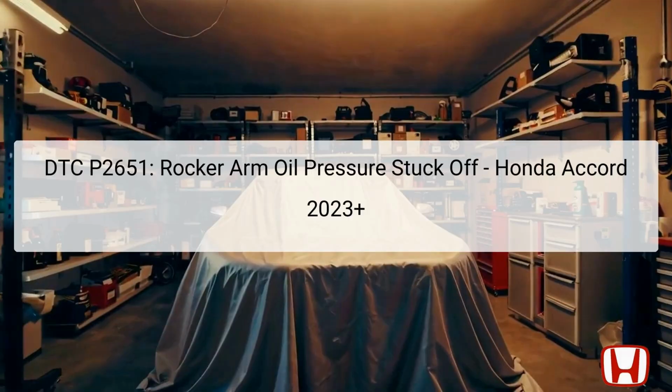Welcome to this troubleshooting guide for DTC P2651, which indicates that there's a problem with the rocker arm oil pressure in a 2023 or newer Honda Accord. This diagnostic trouble code means that the reading from the rocker arm oil pressure sensor remains low when the rocker arm oil control solenoid is activated. The Powertrain Control Module, or PCM, recognizes this irregularity and subsequently stores the error code.